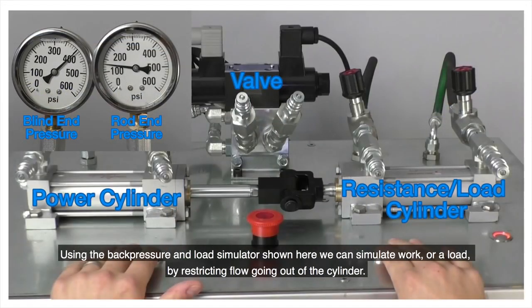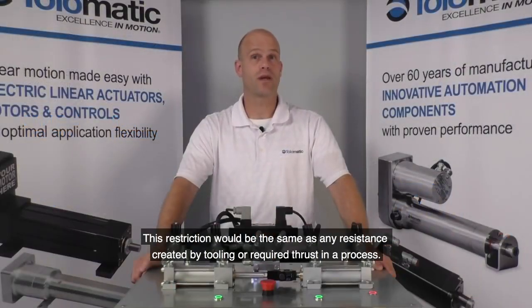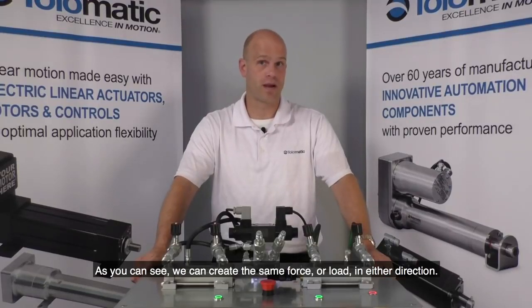Using the back pressure and load simulator shown here, we can simulate work or a load by restricting the flow going out of the cylinder. This restriction would be the same as any resistance created by tooling or required thrust in a process. As you can see, we can create the same force or load in either direction.